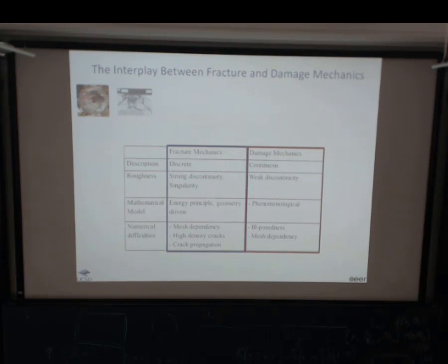In that softening region, as you can imagine, the derivative becomes negative. So in simple terms, the material now has a negative Young's modulus. That will then change the type of PDE. If you have an elliptic problem, it loses ellipticity, depending on whether you consider the dynamic effect or not. But typically, you lose ellipticity. So mathematically, the problem is ill-posed, and there's really no unique solution unless you find a way to regularize. So there are all these issues that need to be addressed.